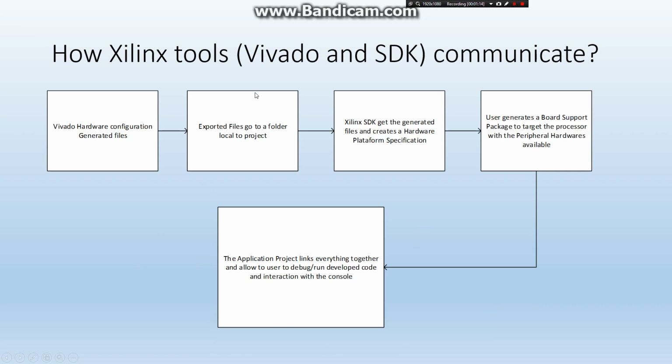So how is Zynq going to do that? You're going to go to Vivado, the first program from Zynq that you're actually going to use, and create the hardware configuration files. Then you're going to export those files to a folder after you design your hardware in Vivado, and launch your Software Development Kit to program and target your processor with the C code.